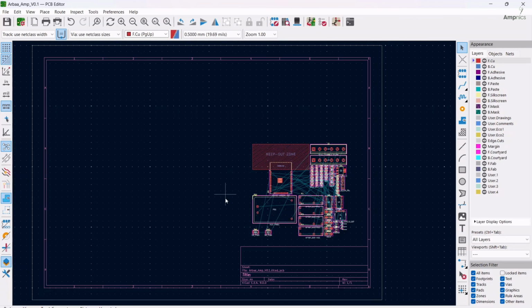We will start placing our devices on the plane. Okay, so here we will make our outline and all. We have to do proper placement of the components so that our PCB works efficiently. There are a few considerations for using decoupling capacitors, for using an antenna, and for using a power supply in your PCB. Okay, so first I will place the proper components. Once my placement is done, how can you do that? Basically you just have to click here.